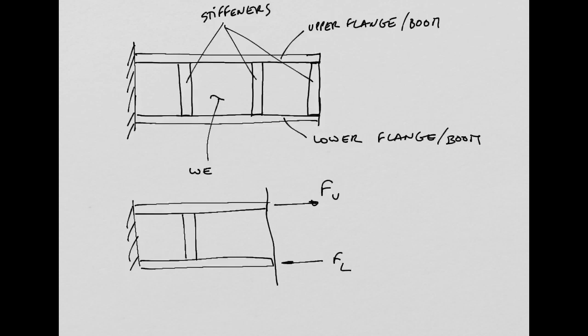These forces are going to be equal to the bending moment in this section divided by the height h, which basically is this dimension, right? If you do the equilibrium summation of moments about this point, you can easily get, don't forget you will have here the bending moment M, this equation, right?